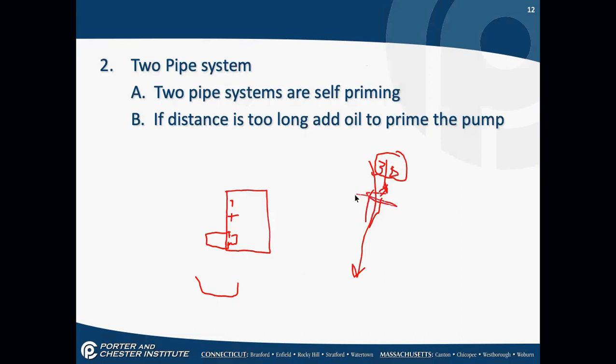Once you close the bleed valve, the flame will start, because the bleed valve prevents oil from going to the nozzle. And because you've used the same wrench to close this bleed valve, you never have to worry about forgetting to take off the jumper. You have the jumper in your hand.